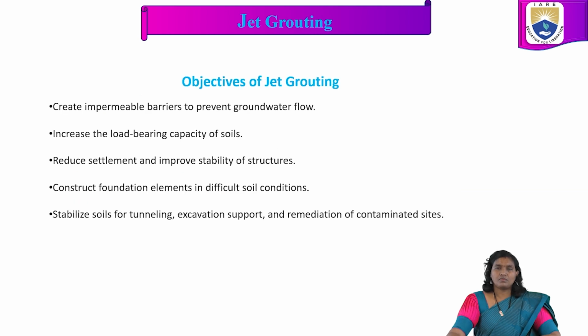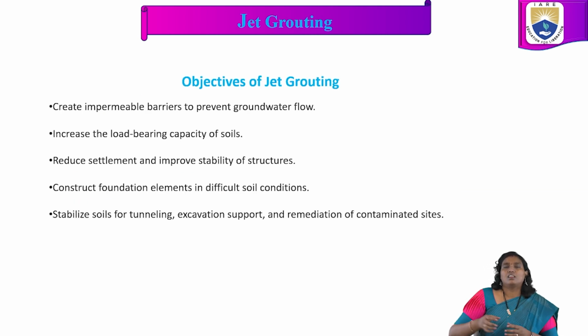In this lecture, we are going to understand how to create impermeable barriers to prevent groundwater flow by using jet grouting, and also how it increases the load bearing capacity of soils, reduces settlement and improves stability of structures. We will also see how to construct foundation elements in difficult soil conditions, and stabilize soils for tunneling, excavation support, and remediation of contaminated sites.